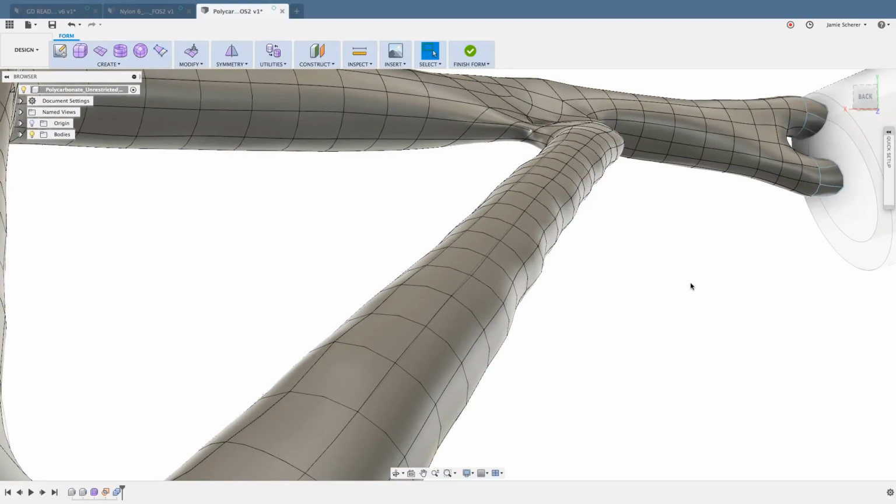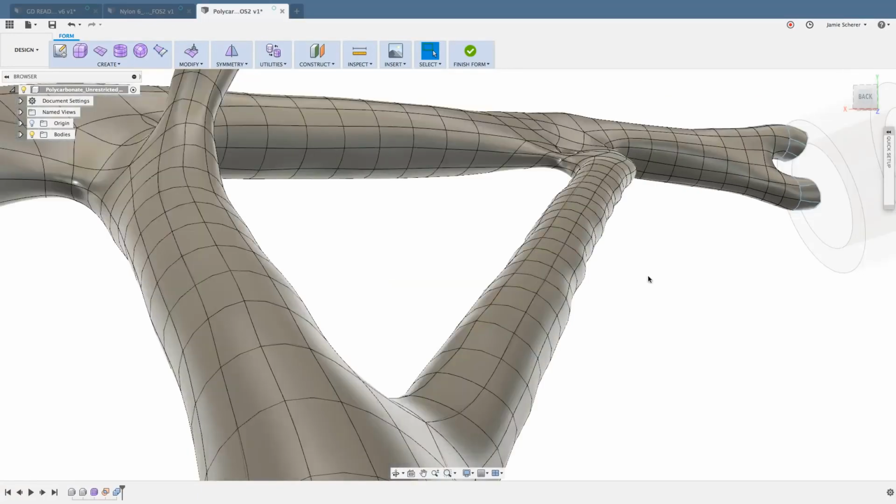Now, again, as a quick sidebar, when we're working with generative design results, we're solving for additive manufacturing, subtractive manufacturing. So either would be fine. And maybe we don't mind that there is kind of this uneven topology that's giving me a little bit of a ripple on those struts. But if you're like me, you want to fix it. And if you're just a sculpt environment or a product designer that's here because you want to learn how to use the sculpt environment, well, fantastic. I'm going to teach you how to refine and start to make simple edits to this geometry so that you can get better control over the results.